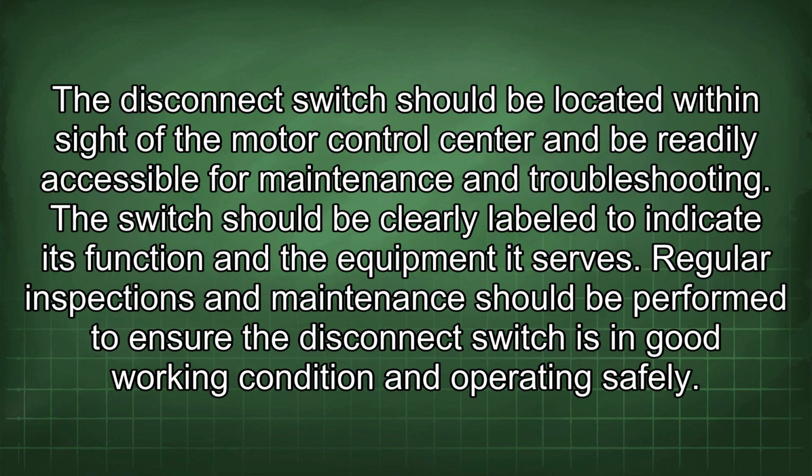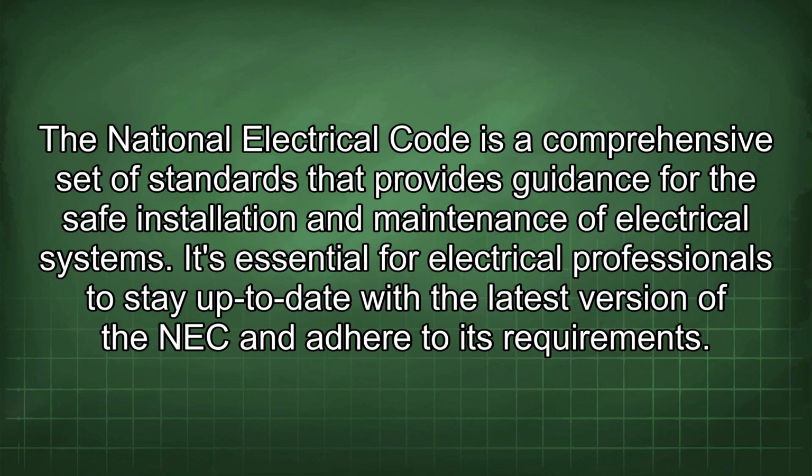The disconnect switch should be located within sight of the motor control center and be readily accessible for maintenance and troubleshooting. The switch should be clearly labeled to indicate its function and the equipment it serves. Regular inspections and maintenance should be performed to ensure the disconnect switch is in good working condition and operating safely. The National Electrical Code is a comprehensive set of standards that provides guidance for the safe installation and maintenance of electrical systems. It's essential for electrical professionals to stay up to date with the latest version of the NEC and